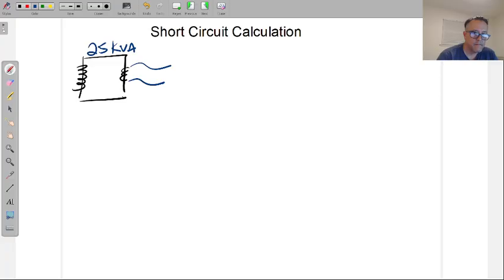However, if it's a 240 volt circuit like a house, the calculation actually only is done on one of the phases, not both of the phases. All right, the calculation is we're only concerned with one of the phases. I mean, something to know, but at the end of the day, I'm just going to give you a bunch of numbers anyway, so whatever numbers I give you, you'll run the formula through the numbers. But that's how it actually goes down.